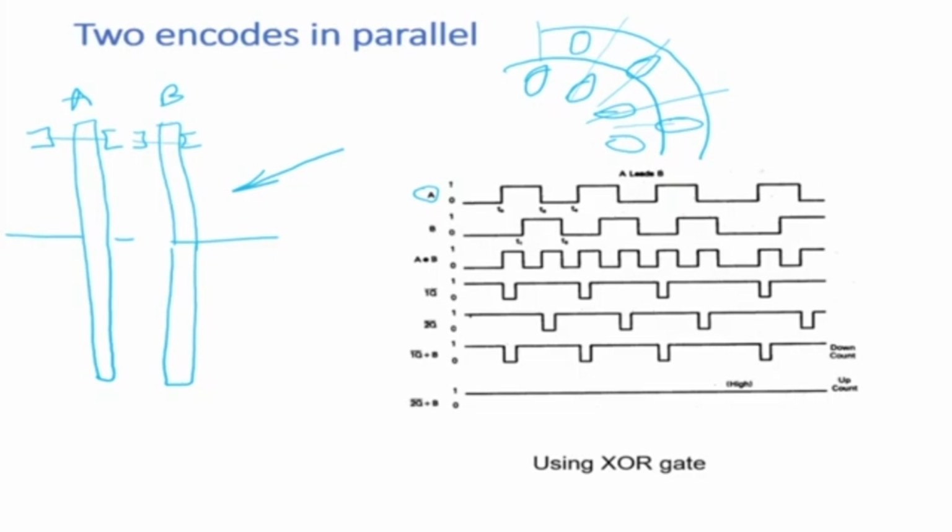So whenever it is rotating, when the motor is rotating or the joint is rotating, what would happen is these square waveforms are going to come. Now we have two of them, A and B, and because of this phase shift, the B will be lagging A. So this will come after some time. The B will come because of this phase shift. So here first A will come, then B will come. And that is being seen here also.